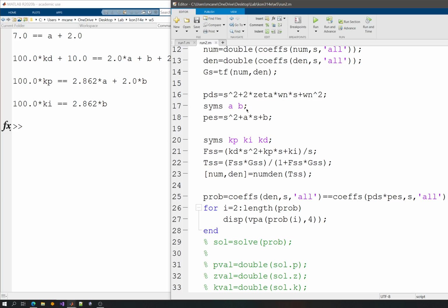What conditions can I come up with so that A and B will be chosen that way, and the closed loop system will be stable, since the stability of the closed loop system is my first priority. If I don't have a stable system, then the design is not possible. Before I try to set the settling time and overshoot and so on, I should first assure that my family of controllers is stable.